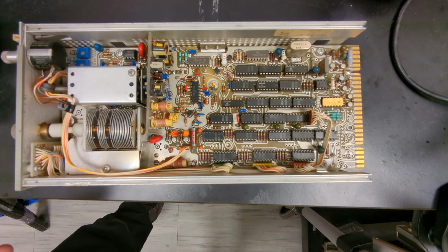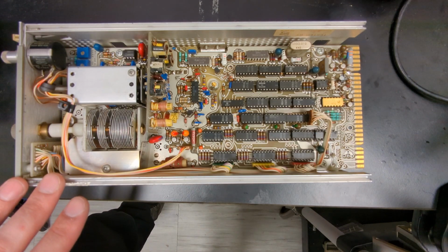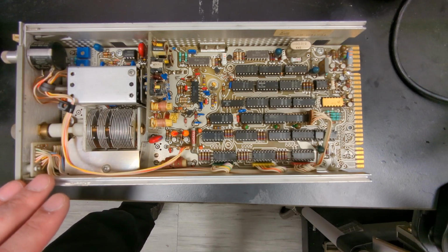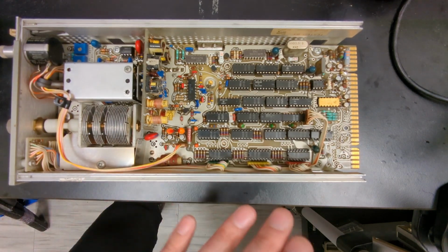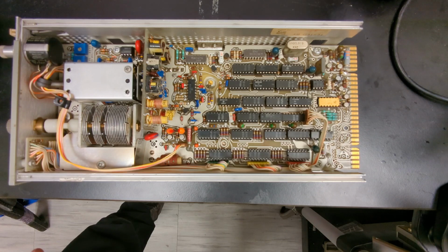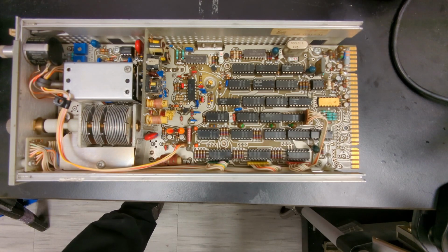So we're looking at the voltages, and they are low. For the 5.2 volt rail, I think we measured like 4.7. For some of these ICs, like these CMOS counters, their data sheet has a minimum of 4.75 volts to run them, and the drivers for the 7-segment LEDs, the data sheet that I found didn't give a minimum, but says VCC should be 5.25.